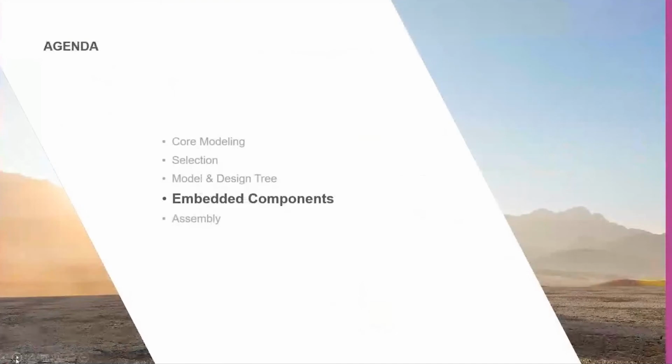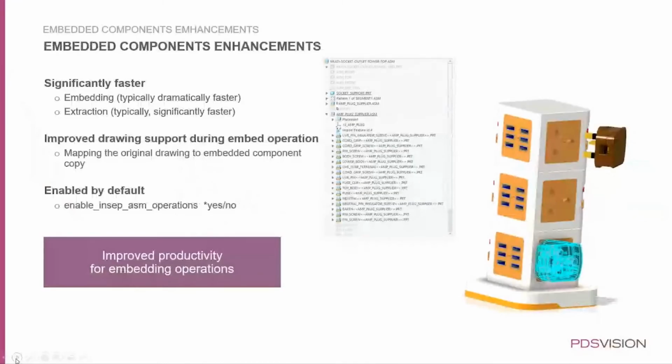Then something completely different. We had, with Creo 8, a thing called embedded components, which simply means that if you have, let's say, a printed circuit board or some other components, like a diesel motor, coming from another design department or subcontractor or some component supplier, and you have, let's say, a STEP file which contains 3,000 different solids, it's possible to flatten the structure, and that is still true. But with Creo 8, it existed, yes, but the performance wasn't so great.